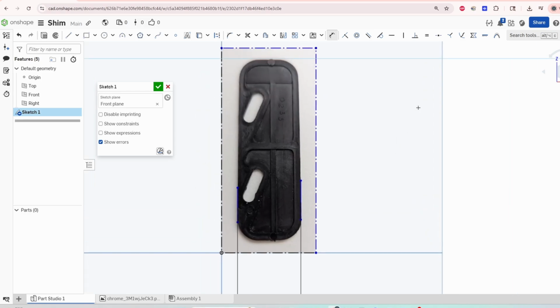So let's start creating the square. I'm going to go from here all the way up here, and because my camera was a little skewed perhaps, I'm just going to go with the outside here. It should be fine, and we'll match this up in a second. So let's put some fillets on here. Let's go over here to sketch fillet, and we'll just match up this fillet, whatever it is. There we go. We got like a 7. Perfect. And so I'll click there,